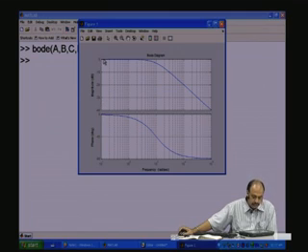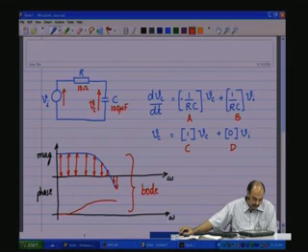So, this particular circuit does not attenuate at this. When you say 0 dB, during this portion the circuit does not attenuate, meaning whatever is applied at the input comes to the output, but as the frequency starts increasing, then it starts attenuating more and more, and as frequencies become higher and higher, it starts attenuating more and more. In fact, it is also evident when you go back to the circuit, have a look at the circuit, you see here this is the capacitance and we are talking of output across the capacitance.